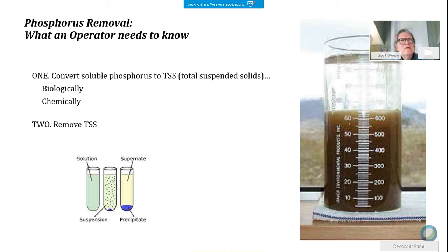People are buying BOD as some kind of a chemical compound. Me, I'd look for a way to take some of my waste sludge and see if I couldn't get that to digest a little bit, break some of the cells down, and maybe get something that's certainly not the most digestible, but something in the form of BOD that I could actually send back into my plant. That's where I would focus. Try to take my waste sludge and see if there's some way between aerobic and anoxic or anaerobic digestion, get those cells to bust down a little bit, and I could feed some of that back in. But I do that with caution. So, very problematic.